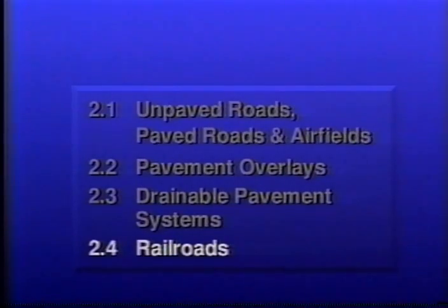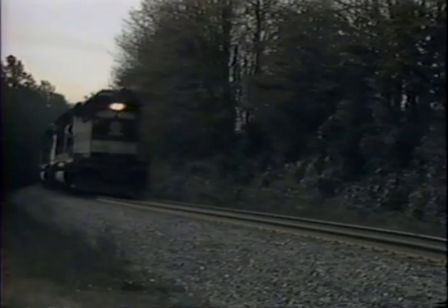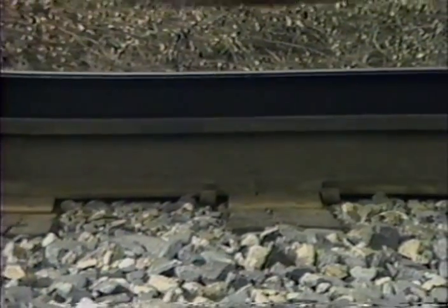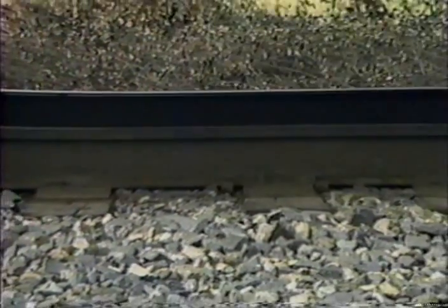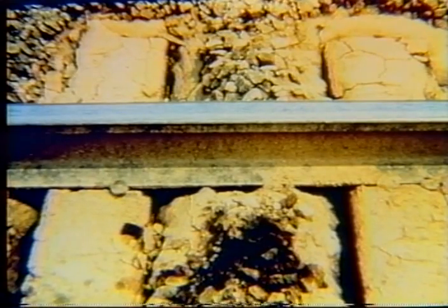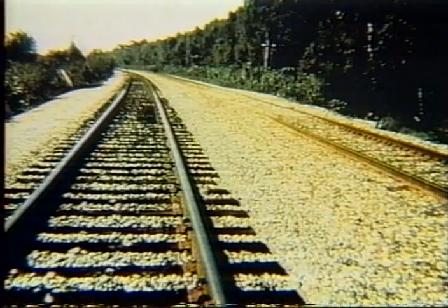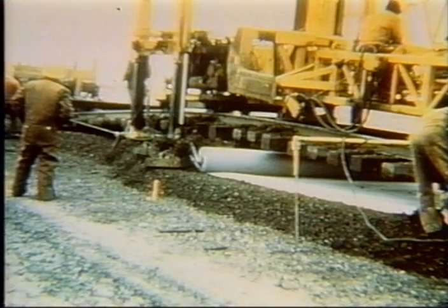Railroad tracks are a punishing environment for any material, natural or geosynthetic. The vibration caused by heavy wheel loads on rail tracks creates a pumping action which forces the subgrade up into the stone ballast supporting the ties. Traditionally, a sand layer was used to reduce this pumping. Now, geotextile filters and separators and reinforcing geogrids assist in solving the problem. They can stabilize the ballast and reinforce the track, both in new construction and track rehabilitation.